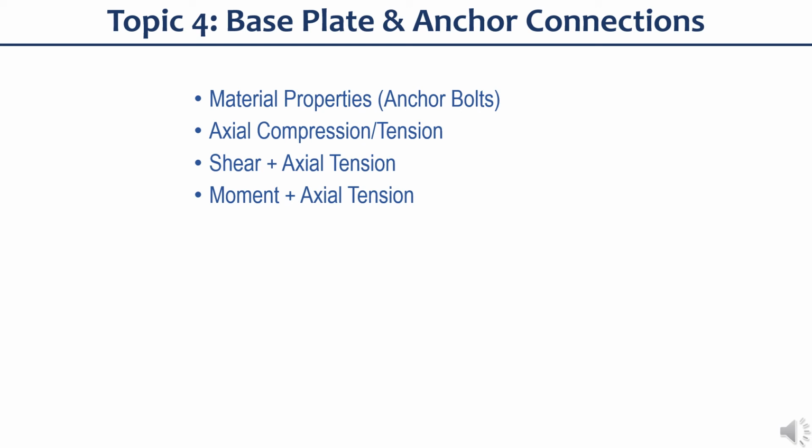For the design of base plates, AISC Design Guide number 1 is the main reference. But for seismic considerations, AISC 341 recently added discussion in the commentary section in D2.6.